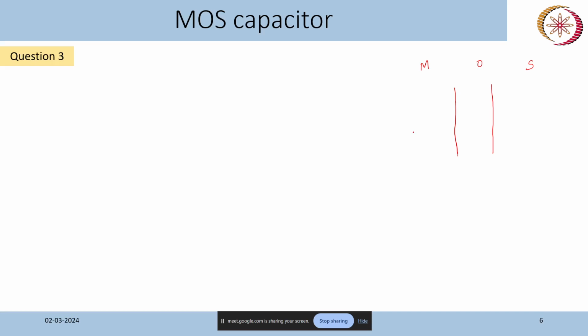The band diagram of metal is described by the Fermi level of the metal, because in metal there is no concept of Ec and Ev, so this is say EFM. Away from the interface in the semiconductor there will be no banding, so let's consider a flat band condition, so maybe Ef is equal to EFM, and it is a p-type semiconductor.